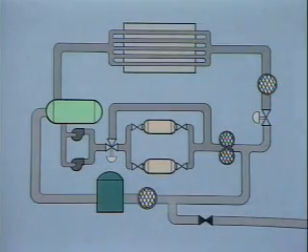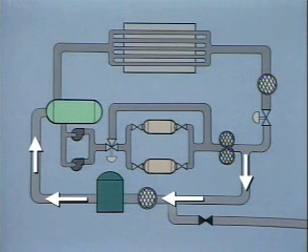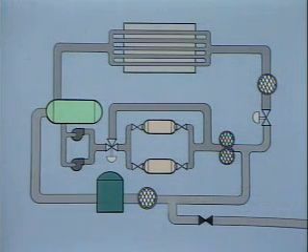If the water is becoming conductive, more of the flow is directed through the demineralizer piping, where minerals are removed and other impurities are filtered out. The supply of water is usually replenished when necessary through a connection to the plant's demineralized water system.